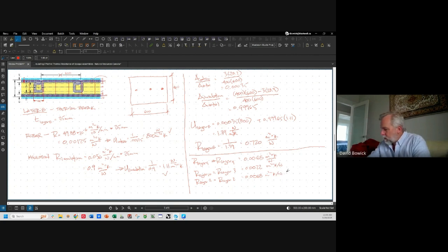Okay, look at this. Our layer 9 and our layer 11 are the same, but they're not the same, right? Our layer 9 has a cold bridge, whereas layer 11 doesn't. It doesn't have the wires going through it. In the concrete, because the concrete's a poor insulator, that cold bridge is a rounding error. In the insulation, it's not. It's meaningful. But in the concrete, it's a rounding error. They turn out, even though we did the calculation separately, to be the same answer. And then layer 12. Outer air film.